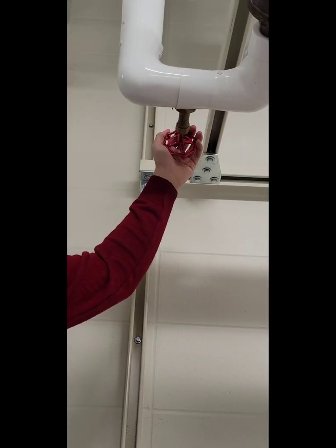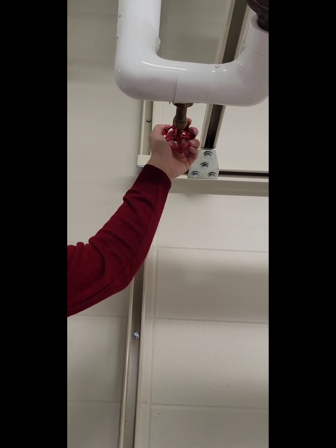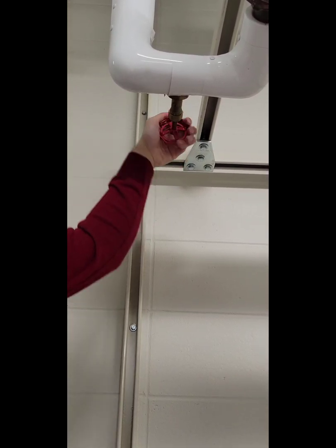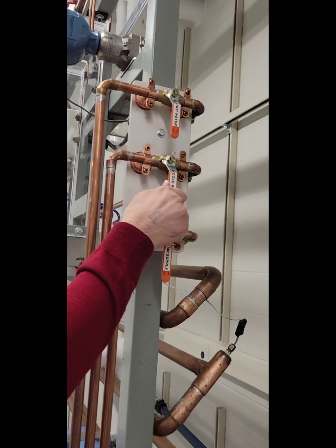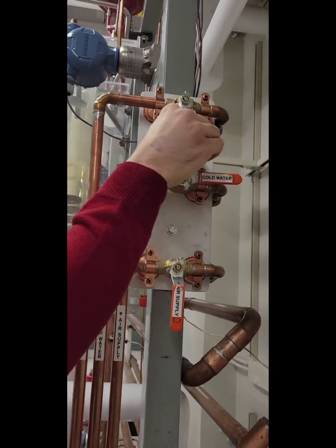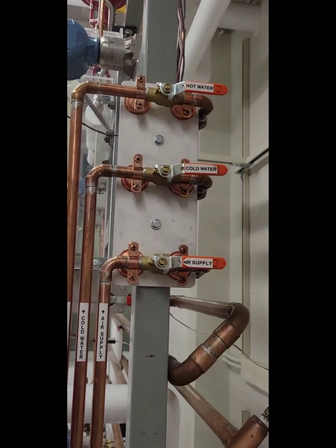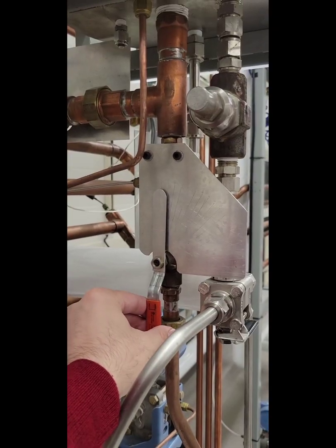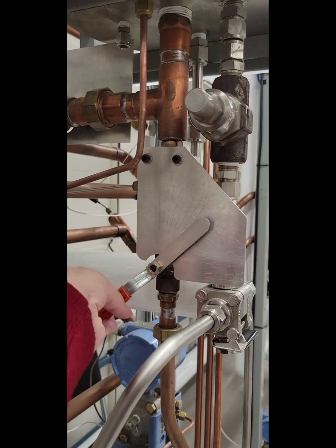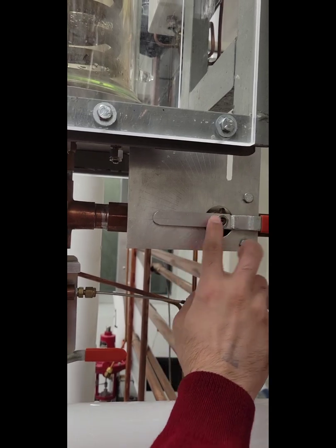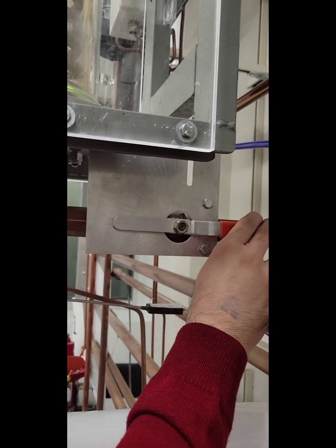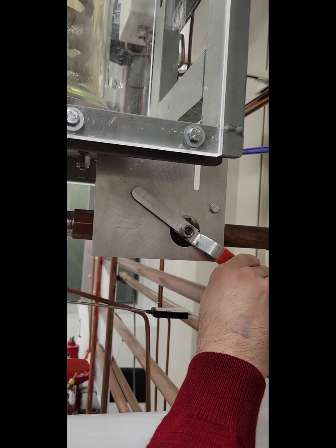Okay, let's do the experiment. To start the lab, we should fully open the steam flow rate hand valve, and also we should open all other steam valves in this lab. Based on the procedure, we should fully close the short hand valve, and based on the table 1 nominal conditions, for the long hand valve we should open until 35 degrees.